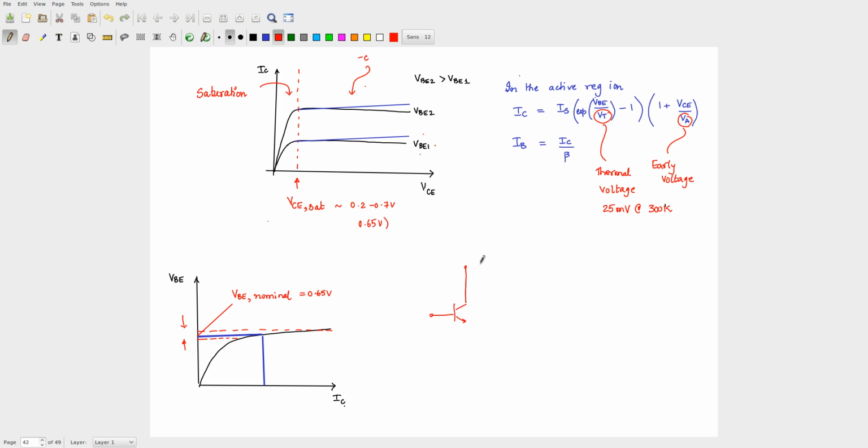Let me call this as VCC, that is 0. Okay. I want to measure my collector current, so I put an ammeter here. That is an ammeter. I have to change my base voltage, so I can cook up an arrangement something like this, right. I can have some variable RB here, and let me say I put something else here, let me call that as some RA, okay, or maybe because in the subsequent discussion we will have RA and RB flipped, so I will flip it now itself. So, I will have RA here and RB like this, right.